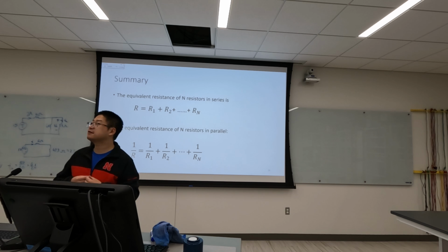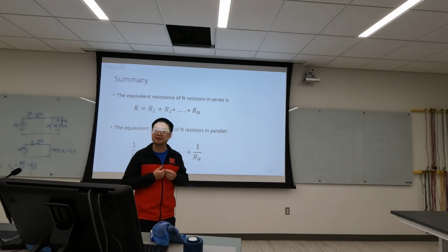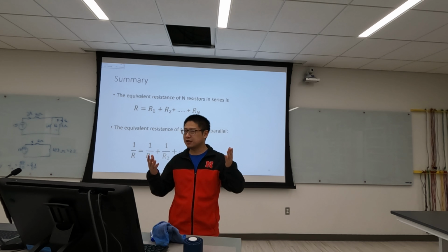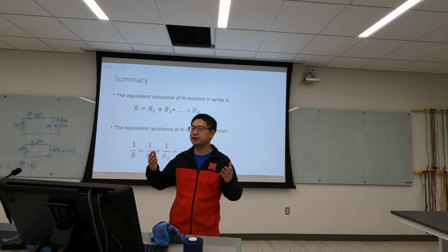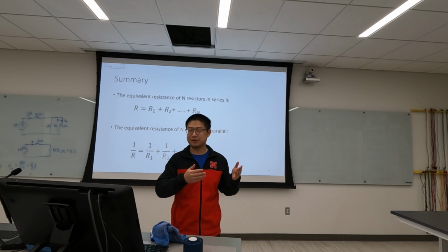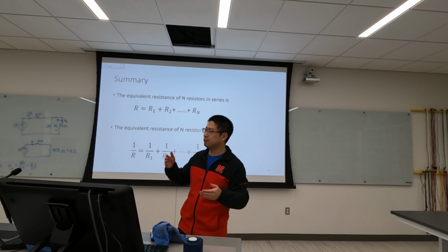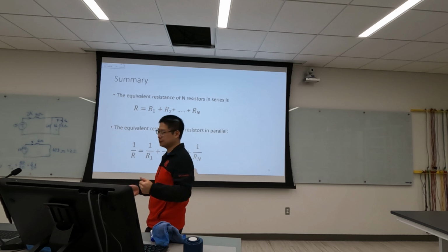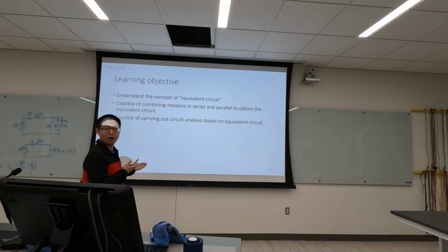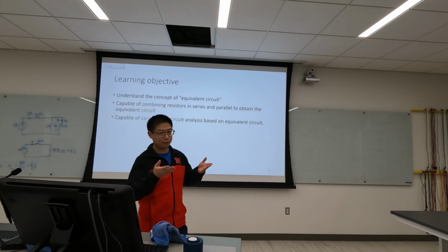So now let's summarize what we discussed today. We discussed the equivalent circuit, and then we introduced the equation to calculate the equivalent resistance for series and parallel connection.